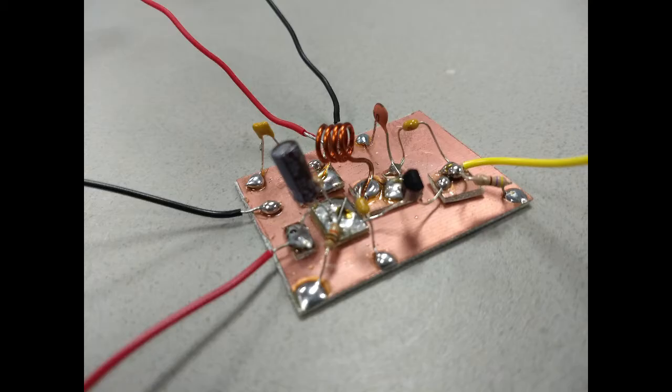For future improvement, we would likely begin by using an expanded version of the circuit, as this version repeatedly relies on the same components for many different functions. An expanded version would separate these functions, allowing for easier analysis and troubleshooting. Additionally, we would likely use a pre-built inductor if possible for better frequency selection. Finally, we would create a more appropriately sized antenna by calculating the wavelength based on the frequency.